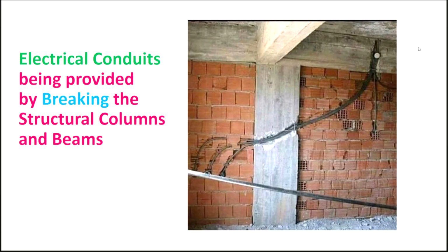Yes, you can talk also, in case you can just put on your mic. What you can see, somebody has taken the cables or electrical requirement or whatever other cables are there through the column, and rather he has cut the column, he has reduced the section of the column, and he has taken his installation to the other side. Likewise, on the beam side also you can see the entire depth of the beam is cut. So my question is, is it permitted? Or what will you do? No, sir, it's not permitted.